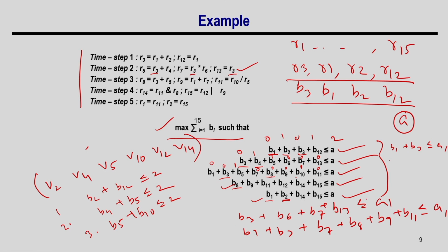You can see here that I am removing the variables whose value is 1, because these are the variables already mapped to memory bank 1. So, I now have to solve the problem for the rest of the variables. The constraints will be reduced, and now I want to solve the same problem. Here I will put it as 9 because 6 of them are already done. Then I try to solve the problem for memory bank 2 and identify the variables which can be mapped to memory bank 2 subject to the number of ports, which may be 1, 2 or 3.